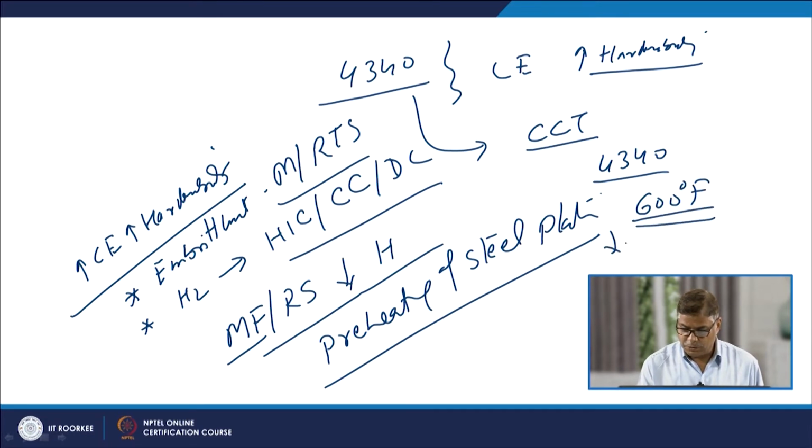so that the cooling rate can be reduced and the formation of bainite is promoted in order to reduce the cracking tendency.